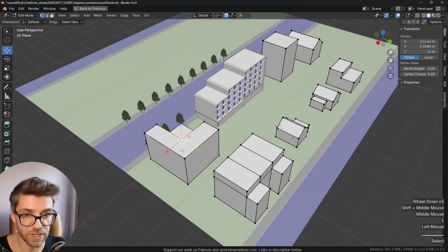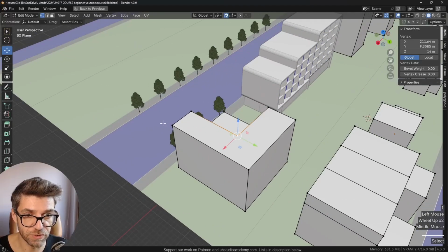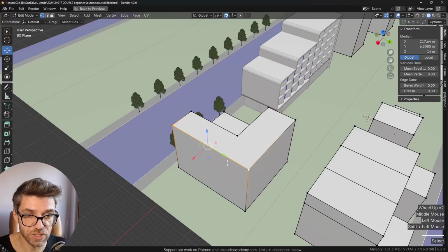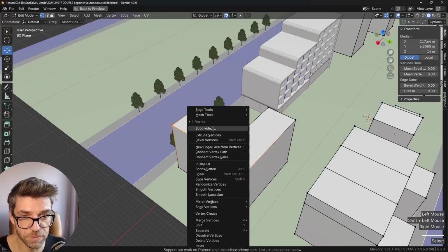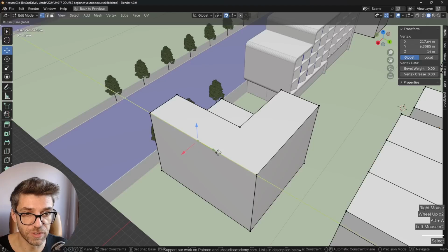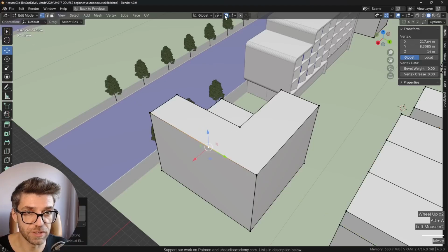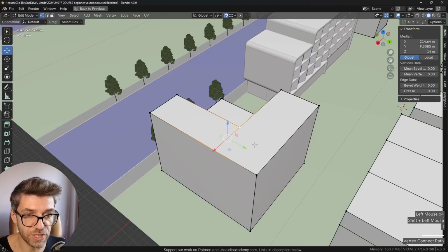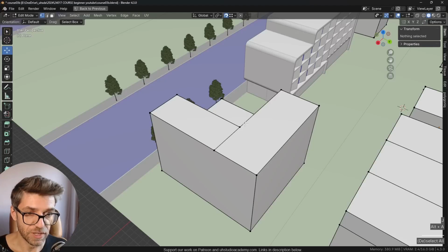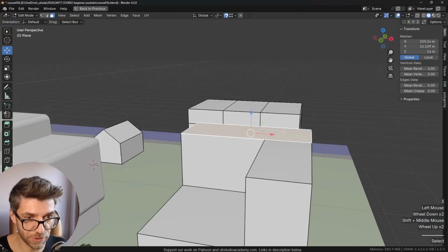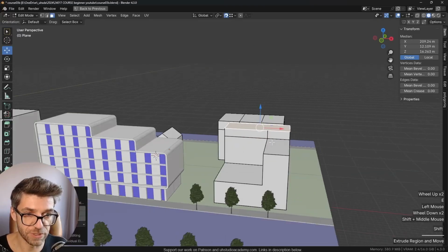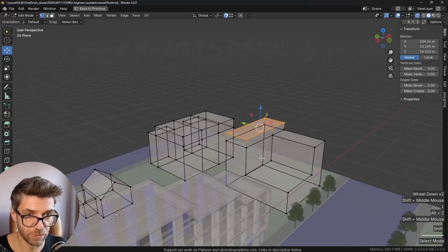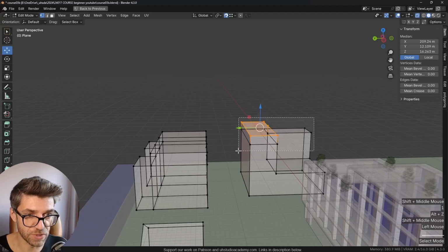I want to create like a nice angle here, a nice edge over here. So I'm going to select this edge, right click, subdivide. We created a new vertex. I'm going to drag it now, and let's go to vertex selection to snap this over here. J is the hotkey to connect them. Found this totally randomly. It's one of the best things that I found totally randomly. Sometimes it happens, doesn't it? And now we're just changing things around ever so slightly.